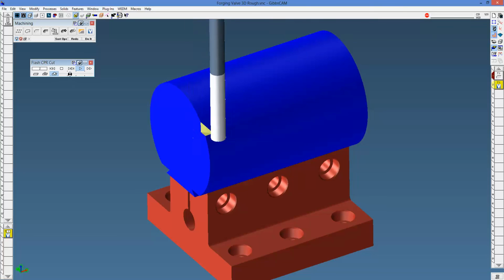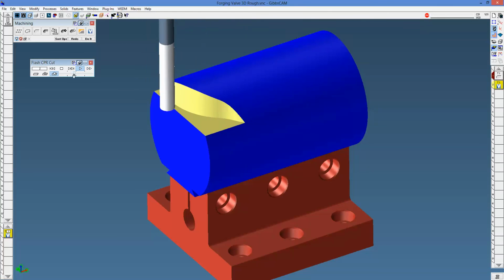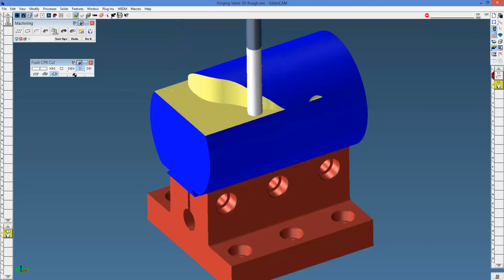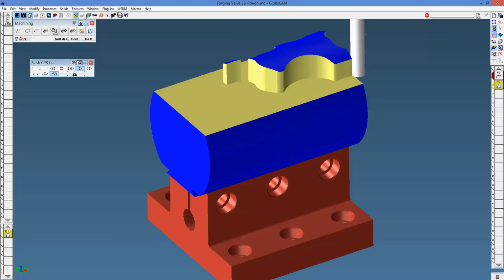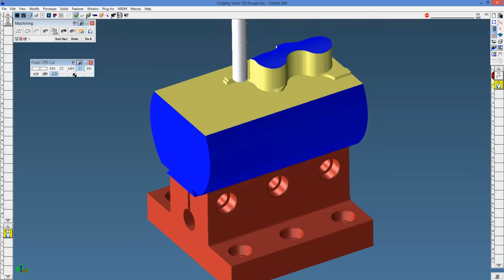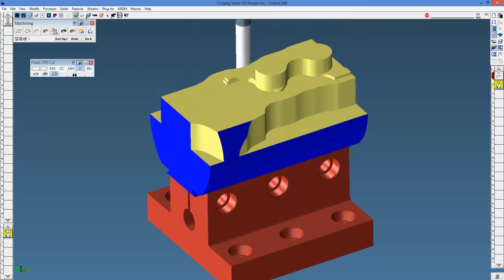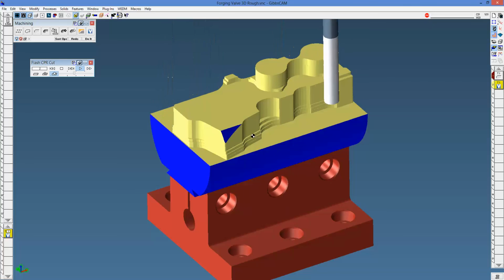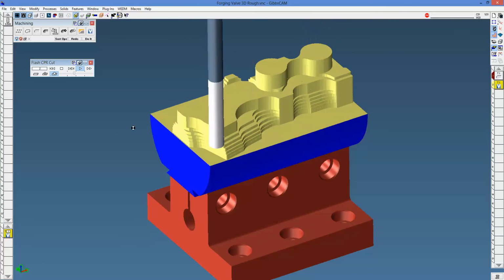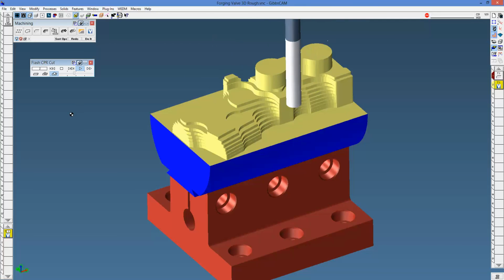is you can see that it's taking some pretty hefty cuts, 1-inch cuts with a 1/2-inch end mill. Right? And it's coming in from the outside as much as it can, which is good. And there's another cut. And now you'll see on this cut in particular, when it's done, it's going to go back from the bottom up and put in that 0.1 ridge height that we specified. And there's the finished product.